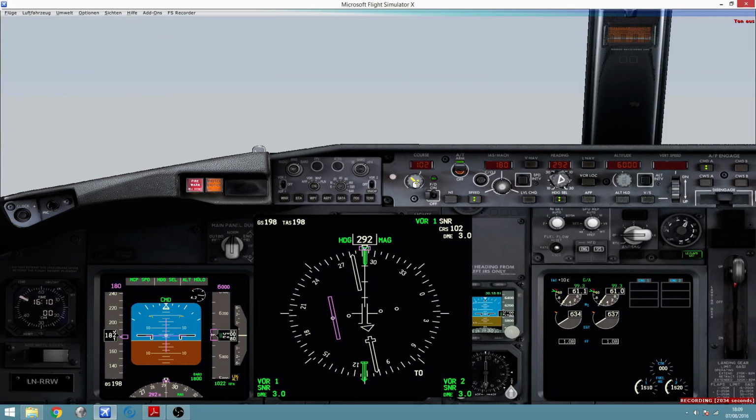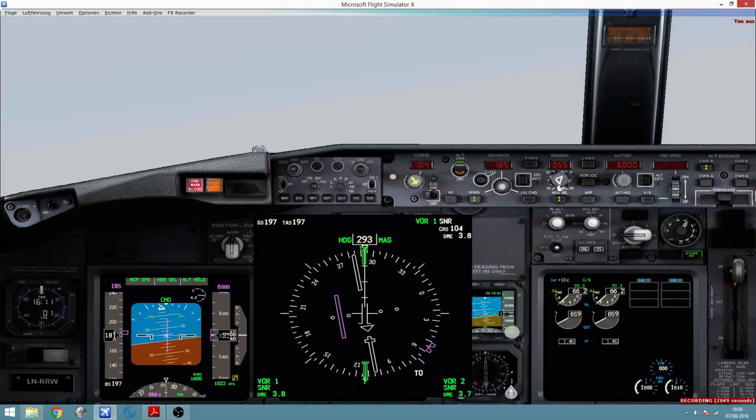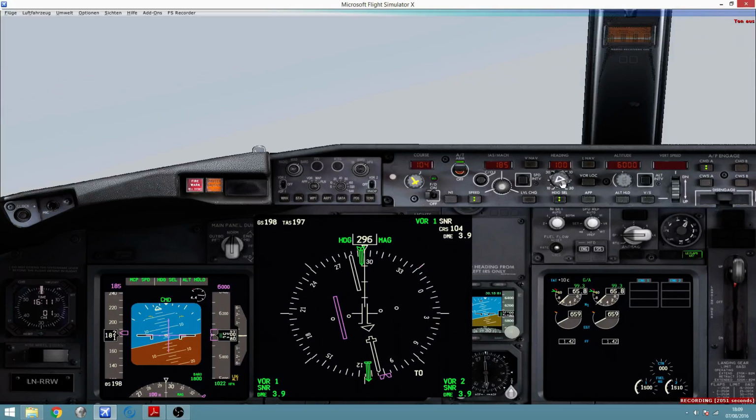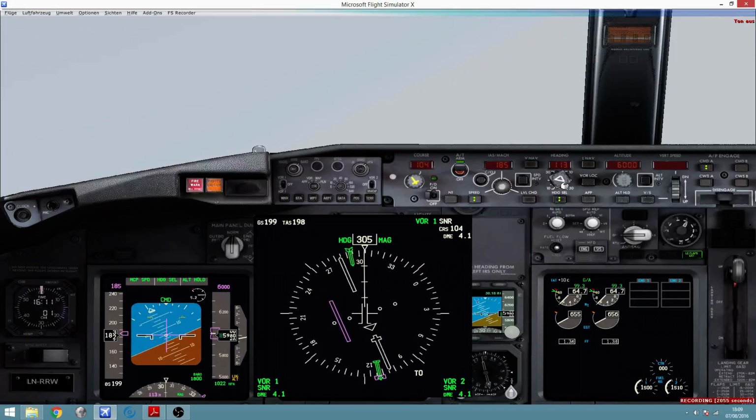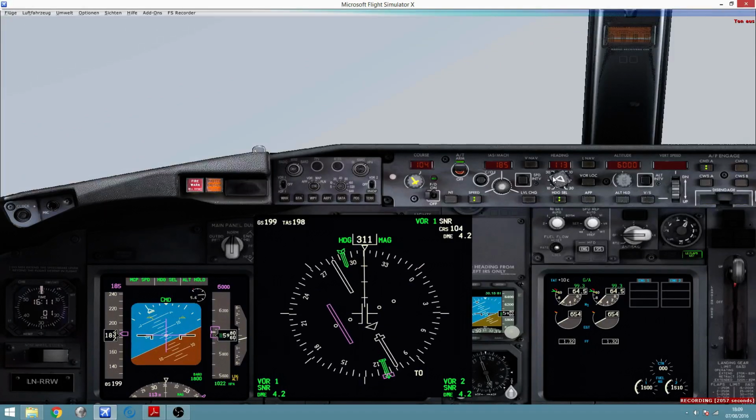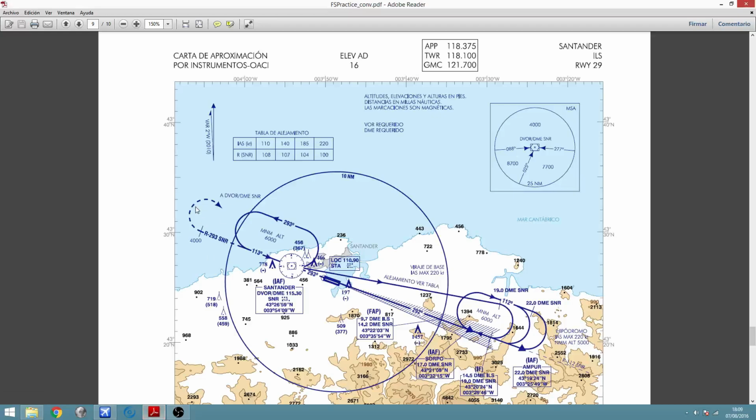Radial 104. 50 seconds now. And I said 185 knots. Okay, so 1 minute, there we go, and now I turn by the right towards the VOR. Good. So I'm going to continue towards the VOR, and from the VOR I will vacate it outbound using that table.